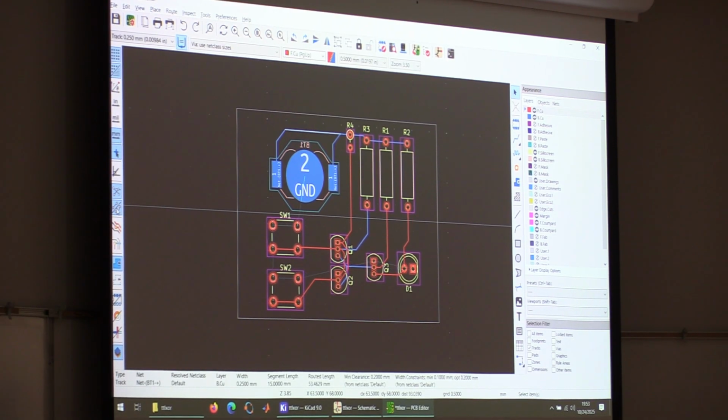Alternatively, if you want them to be straight, you can use this or make them curved. What they represent is a connection that hasn't been made yet. In my case, I've got a bunch of them, mainly between the ground connections, just because I haven't connected all the grounds yet.